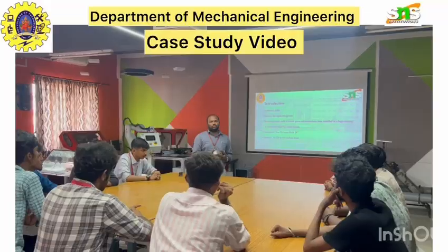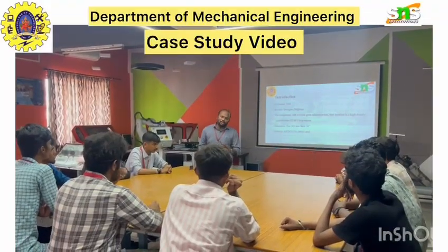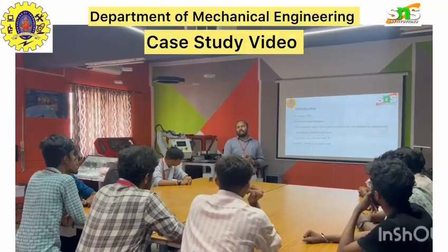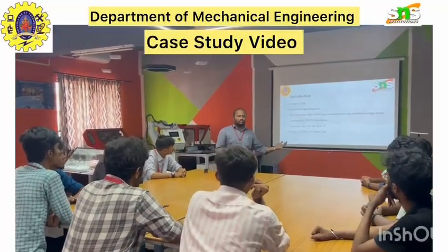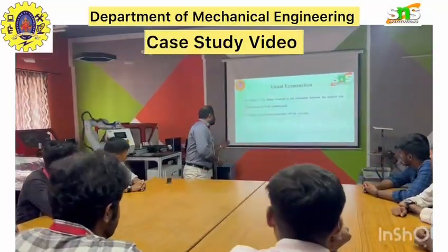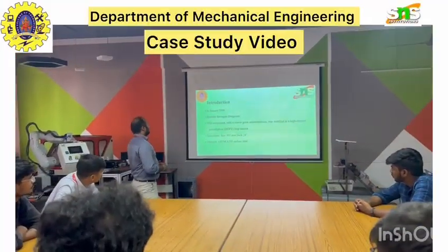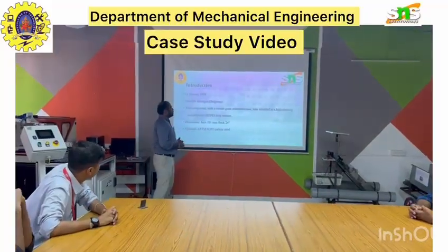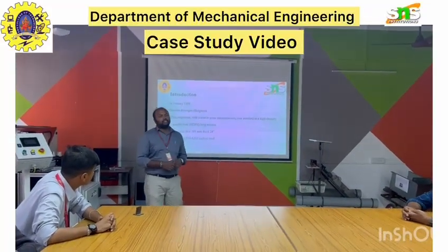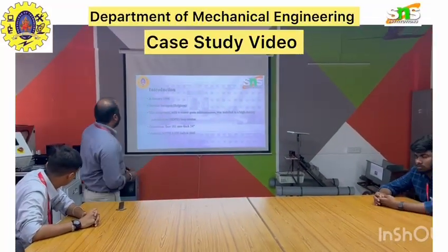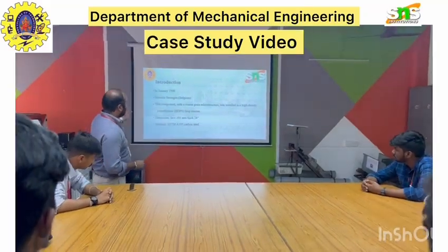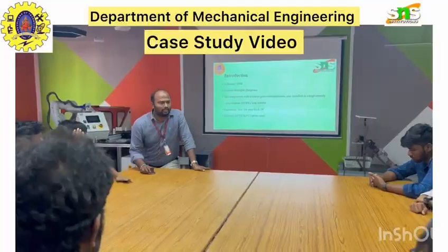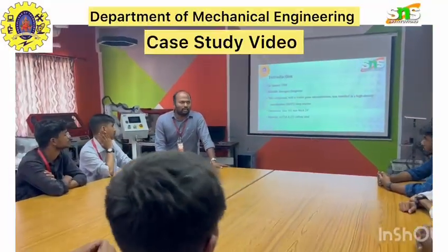This has happened on a welding flange, not exactly due to welding, but sometimes failures can occur due to other processing. Okay, we'll see over it. So this is the introduction. This is the component, a welding flange which has a 4-stage microstructure, installed in the high density polyethylene loop reactor. This is the dimension, and the material is ASTM A105. As I already indicated, ASTM is the American Society for Testing and Materials.